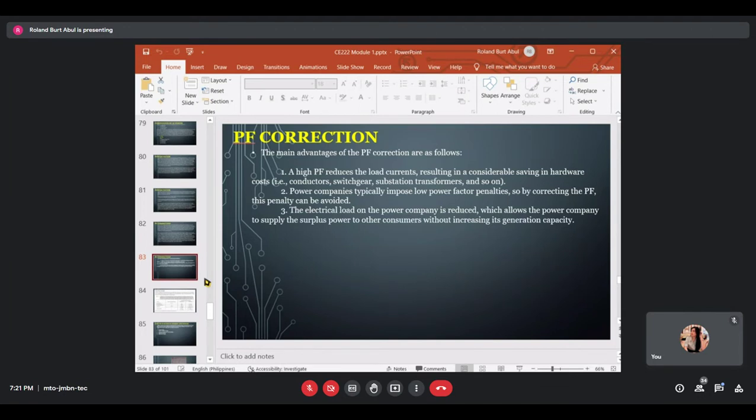Commercial or industrial operations rarely achieve a power factor of 1 because inductive loads from motors, transformers, and light fixture ballasts are common. This inductive effect causes the phase of the current to lag behind the phase of the voltage. A greater lag in current results in poorer power factor. The PF can be improved by adding capacitance to the circuit.